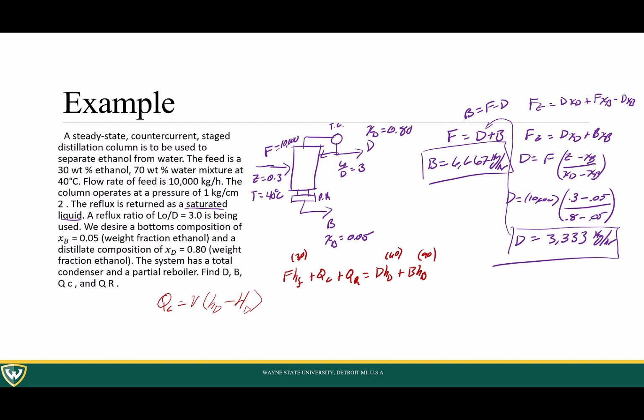Again, same composition, so it's just whether you're going between saturated vapor or saturated liquid. And we need our V, so that's our V1. That's where our reflux ratio comes into play right here. Remember, if we did a balance around the condenser, we have that V1 is equal to D plus L. We also know from our reflux ratio that L naught over D is equal to 3.